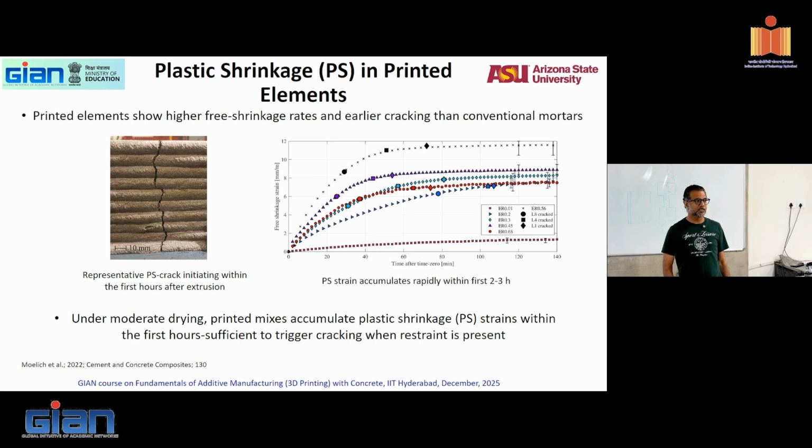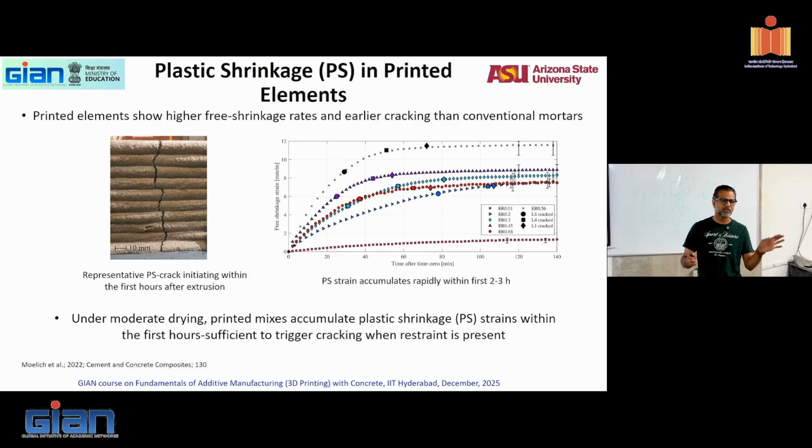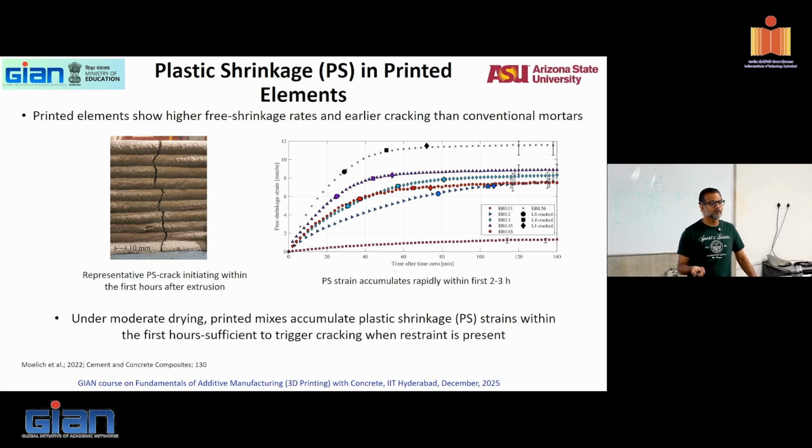Okay, the next thing is plastic shrinkage. We kind of dump shrinkage into a durability characteristic right now because there are not many other durability issues that we deal with. You can see cracking. I showed you this picture earlier. And what is plastic shrinkage primarily due to? Evaporation of water from the surface. Evaporation is dictated by surface area. Higher surface area, faster evaporation, right?